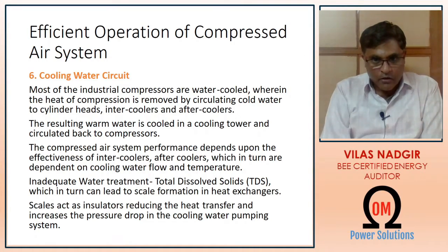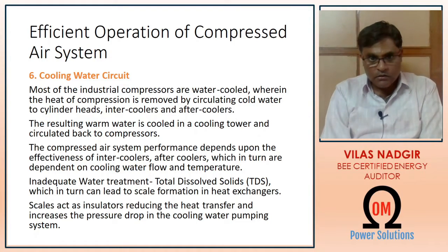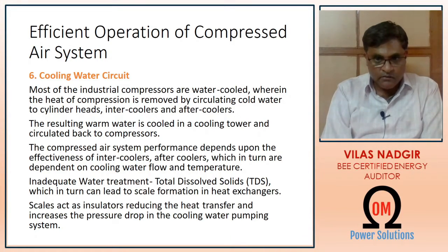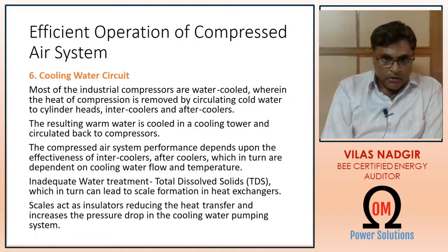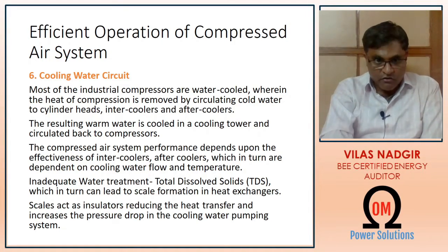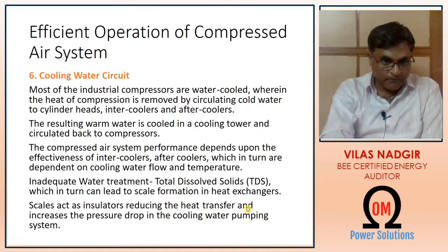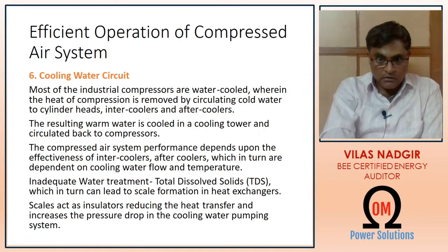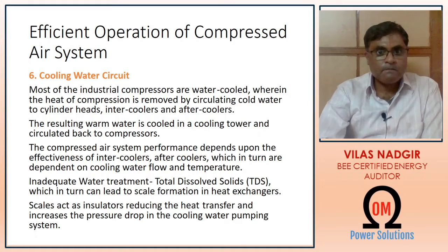We have to focus also on water treatment because if we do not take proper water treatment, then there is a chance of getting total dissolved solids in the cooling water, which will lead to scale formation in heat exchangers. So these scales not only act as insulators in reducing the heat transfer but also increase the pressure drop in cooling water pumping system.